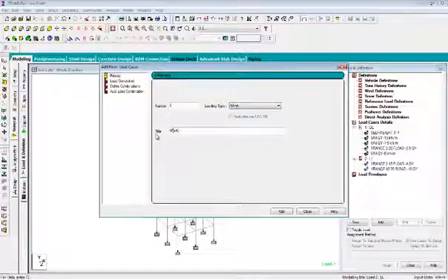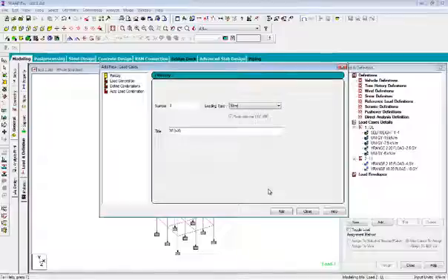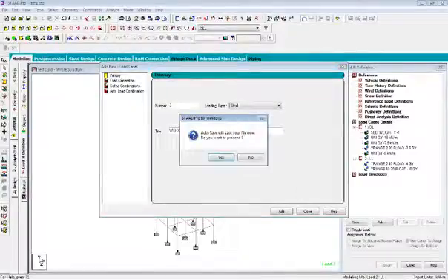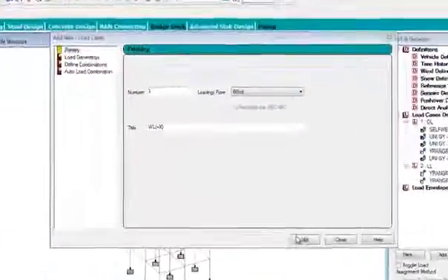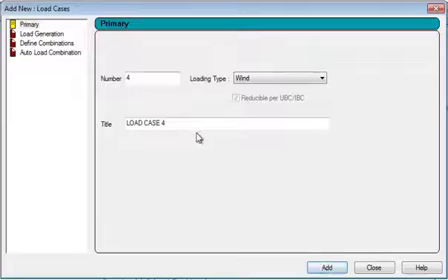Make it caps, actually caps makes it feel good. So let's make it caps. Yes, save, add. Then number 4, also a load case detail, the same one, WL minus X, because you can always know the wind comes from all the 4 directions.